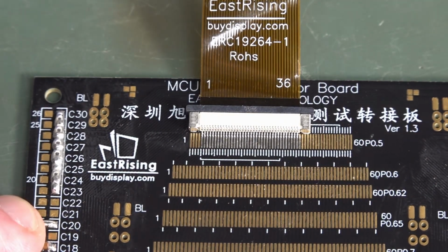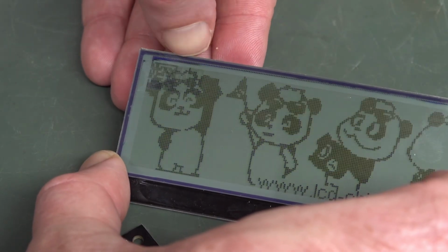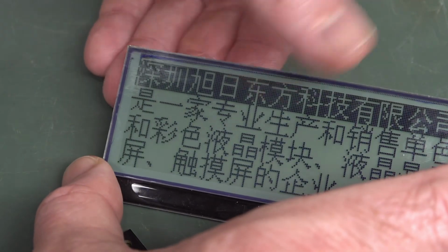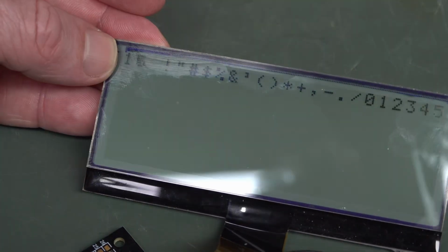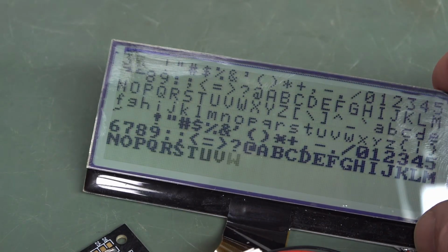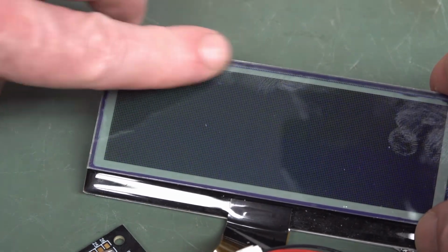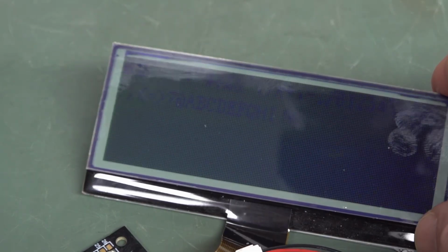Yeah, that bleeding there at the top, that is just some excess liquid crystals outside of the main dot matrix display area. And yes, it is my static charges actually turning those on. So yeah, it's interesting though. And you can see they're outside of the area, because if I turn the contrast right up, you see those at the top there. So just some extra liquid crystals.